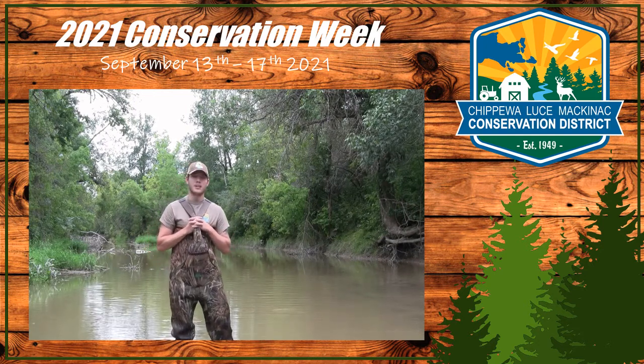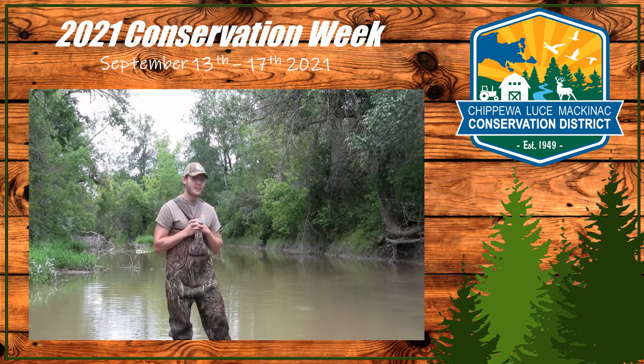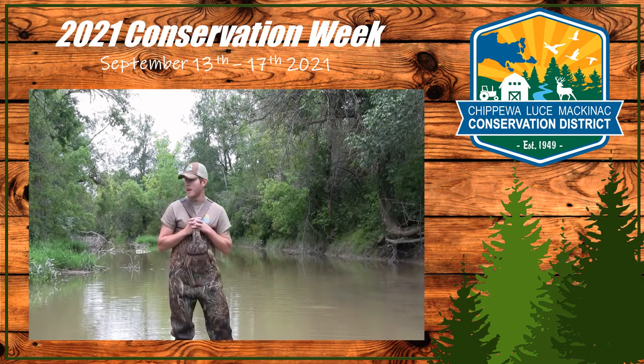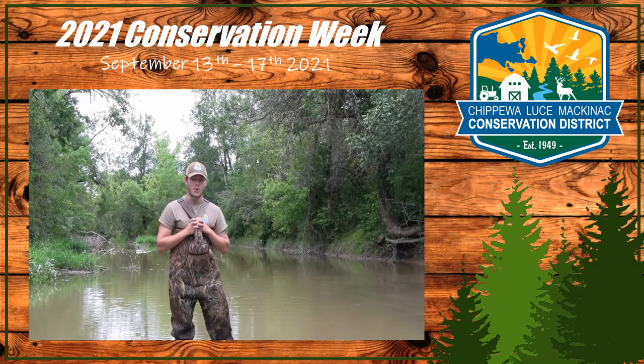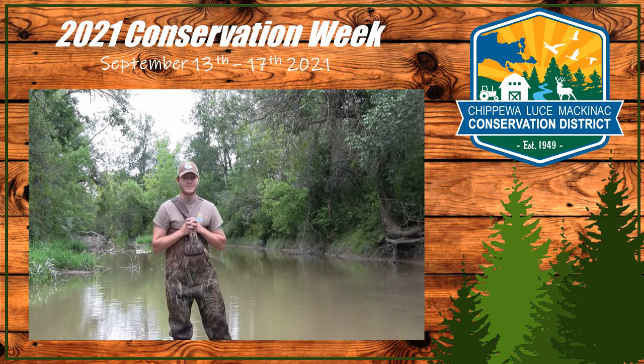We're also in a different soil group here. This is primarily clay soil, so the water is more turbid. There's less buffer along the river system, and there's just a lot more impact along the river itself. So we'll take some measurements here and then compare the results with the first location.